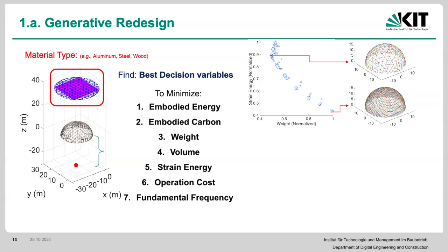redundancy here. It's a crude way of thinking of it: let's say we remove 5 elements of this versus 5 elements of the other one. Which one is going to collapse more? The other one, right? So this is where you're going to see some conflicting information. And then what we get here is referred to as a Pareto front. Okay, so there are methodologies that we can use to get this Pareto front, and an AI-based method for multi-objective optimization is called the non-dominated sorting genetic algorithm, NSGA-II.